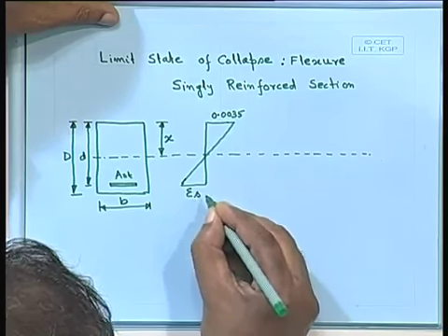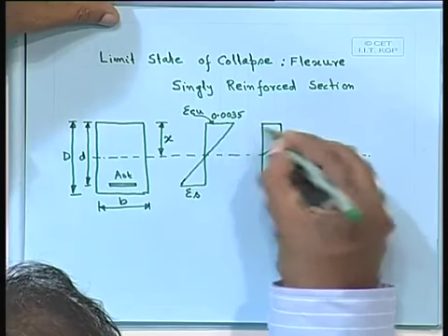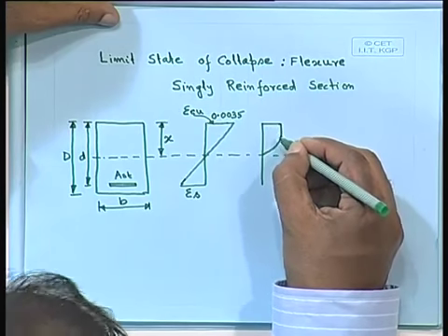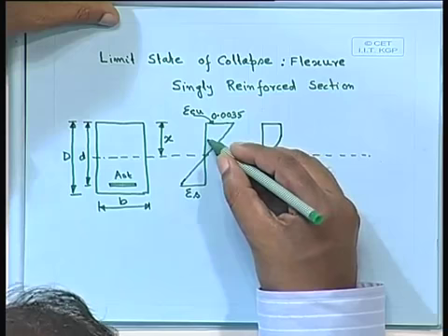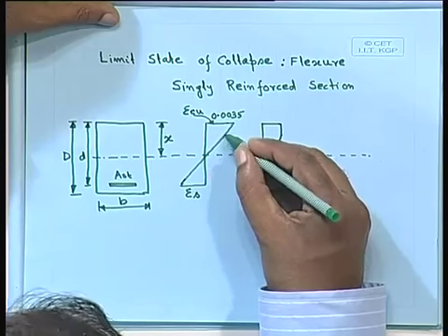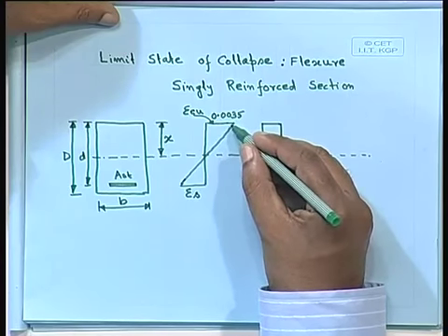What about the stress block? The stress block is the same one which we have shown you, that curve. We have a maximum of 0.0035, and somewhere here 0.002, because we are starting from 0. Finally we shall get the maximum strain allowed, 0.0035, which will never go beyond this 0.0035.